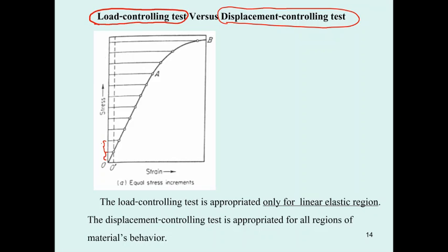At a load of 0.5 kilonewton, the loader asks a friend to read the displacement, then it is increased to 1, and the friend reads the displacement again, then 1.5, 2.0, 2.5, 3, 3.5, 4, 4.5, and 5, while another friend records.